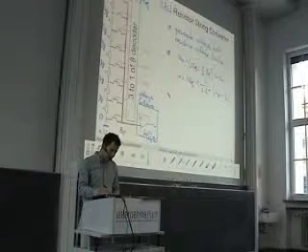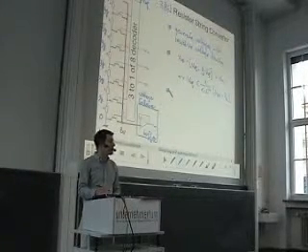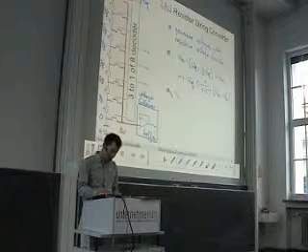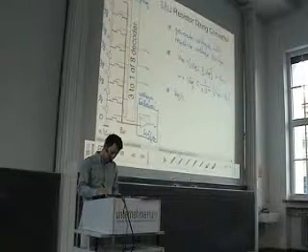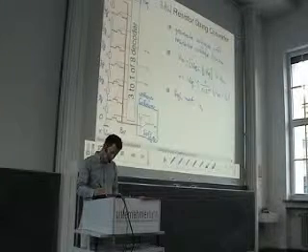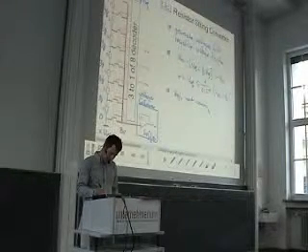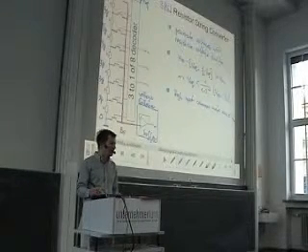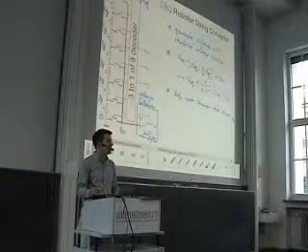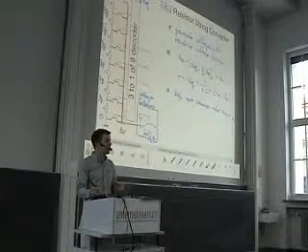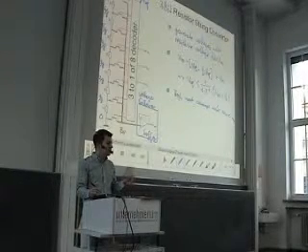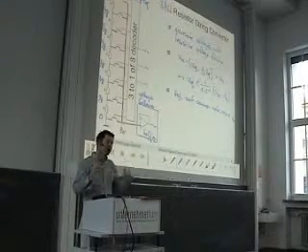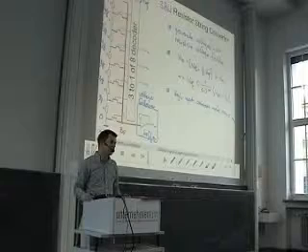So this means that we need a buffer or operational amplifier that has a high input common mode range, which makes the design of this device much more difficult than if you would use it always in a situation where you have a virtual ground, or an analog ground, connected to one node, and the input signal is always around the same common mode range.